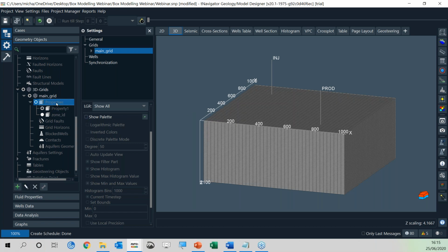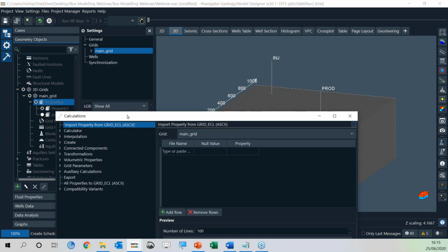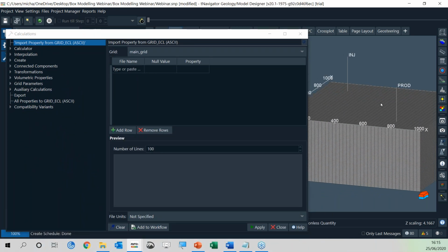Firstly, then we're going to select properties on the top, on the left-hand side, followed by the hammer tool again. And we're going to make the property a value of 0 and the tight sands a value of 1. So we can use those in an if function for our porosity and permeability.